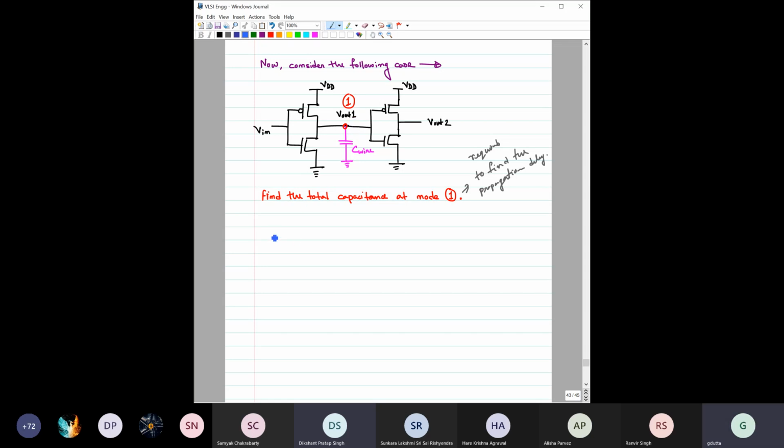Quickly, I need to cover a little bit more. So I can say it is C out 1, the output node capacitance associated with node 1. It would be first the input capacitance of the next stage, C input of next stage, plus C wire, the capacitance due to this wiring, plus C self, because of the capacitances associated with this inverter 1.